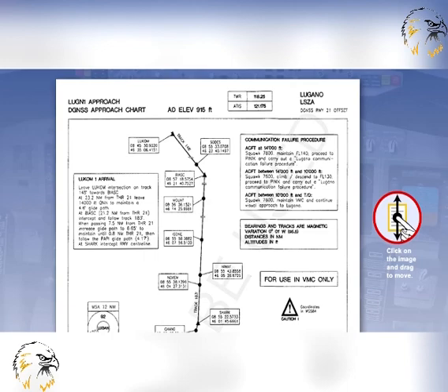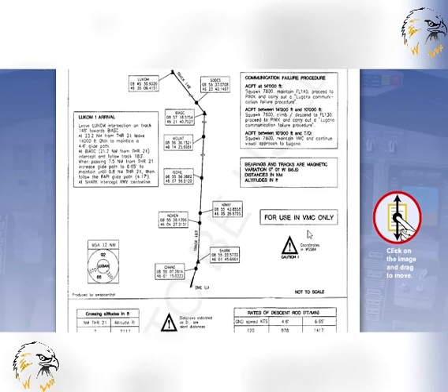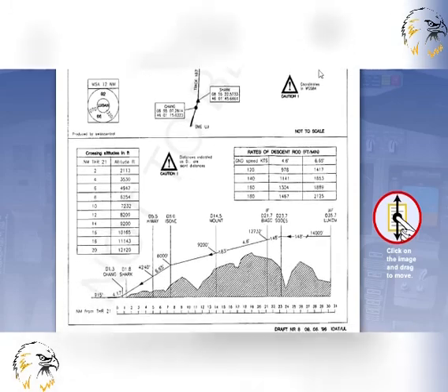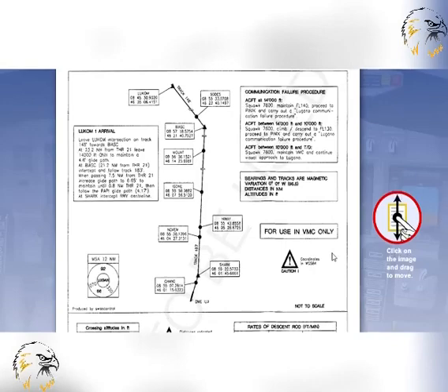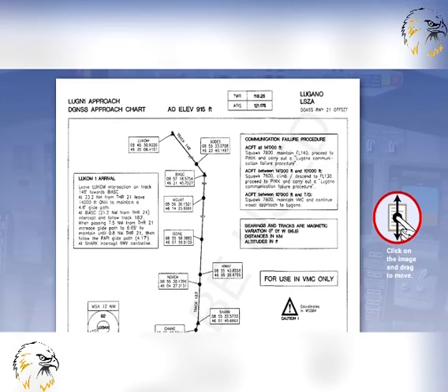The aim is to eventually replace VOR or DME with GNSS. These procedures will use Precision RNAV, known as PRNAV, which may be augmented by altimetry cross-reference, Baro VNAV, to give the precision element to both arrival